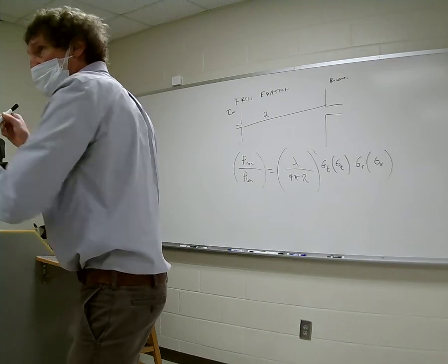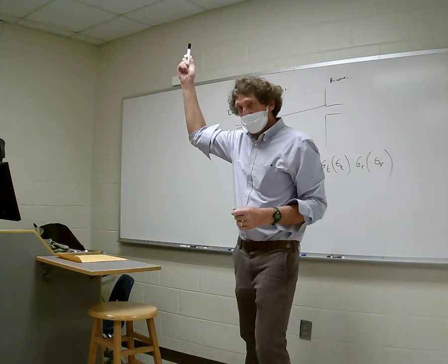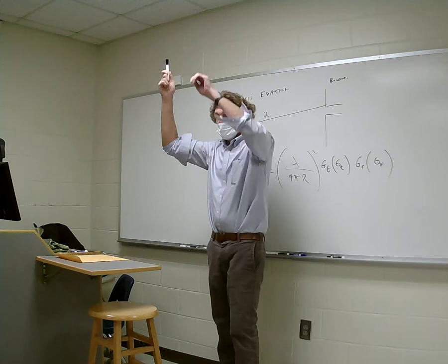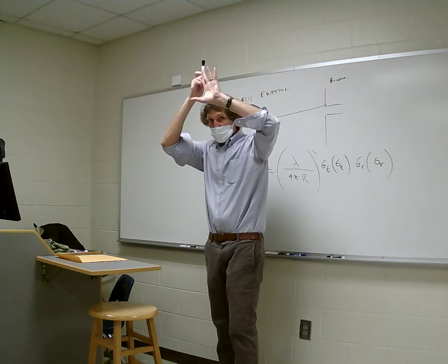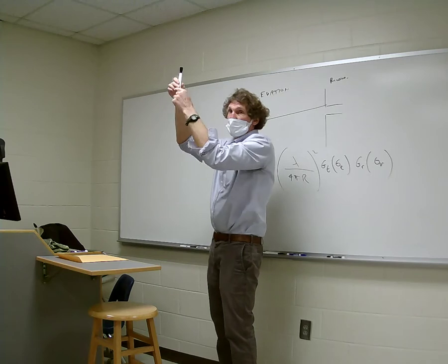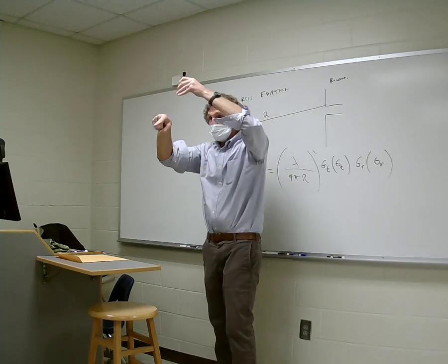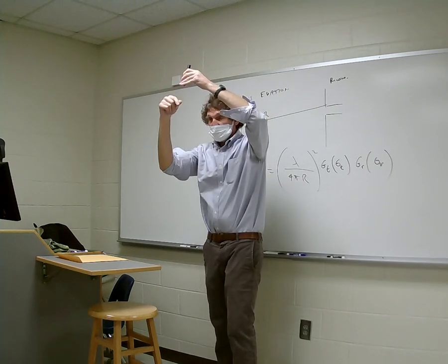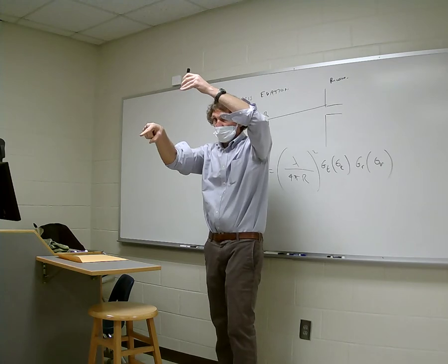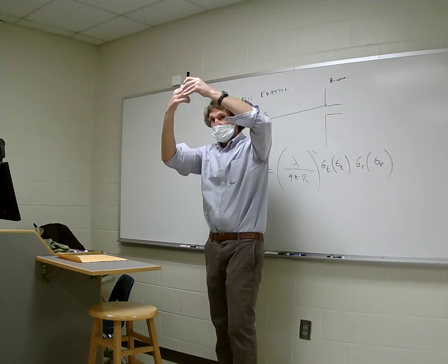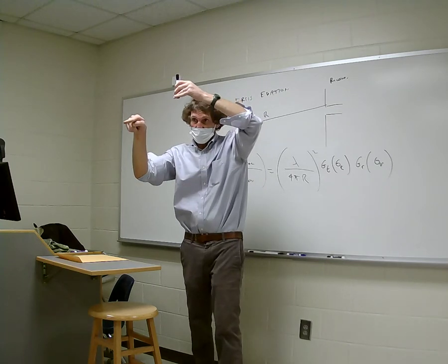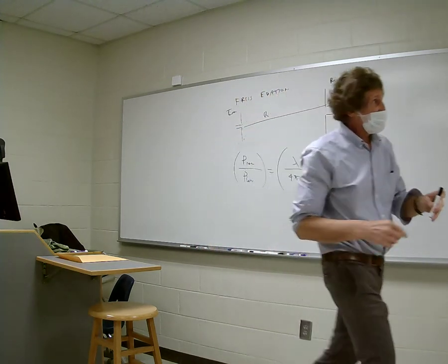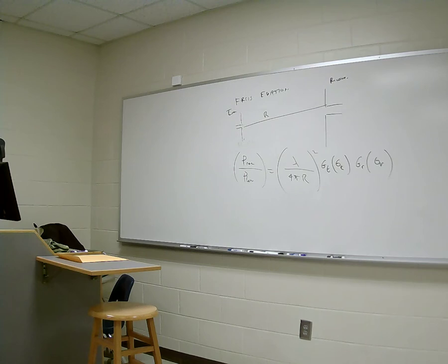Got that? That'll give me the power density. How much is received of that power? I take the electrical size, lambda squared over 4 pi times the gain. What gain? Well, that gain would have to be the gain associated with this antenna. If it's a short dipole, it's 1.5, and it would be the sine squared of the angle that this antenna makes with the r vector. You all follow me? Now, here, I've got the r vector this way.